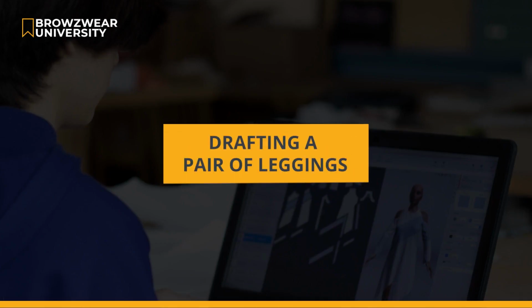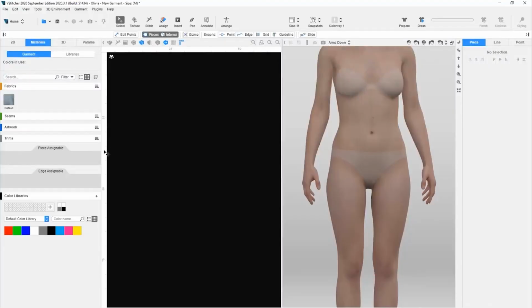In this video, we'll show how to create leggings from scratch in VStitcher using the Guidelines feature and the Pen tool. We begin by creating a new garment file. Before we start, we ensure that the 2D window rulers are enabled. Then we want to create a grid of guidelines to help make it easier to draft the pattern pieces.